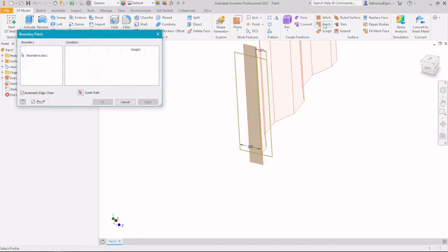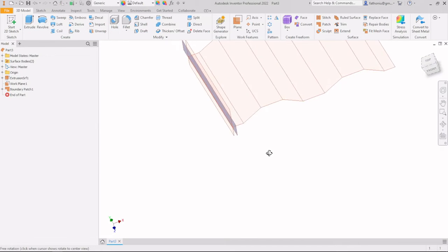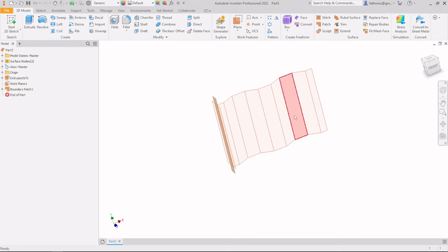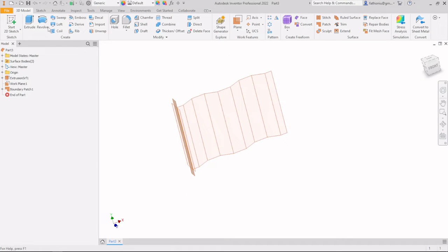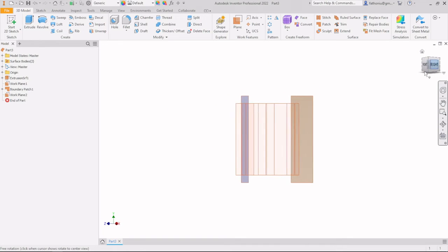To create the surface here, use the patch, select these two patch, click, and okay, then it's converted into what we call a surface. Okay, then same process, we set the plane to this line, and then about the surface 90 degree, yes, there. And after that we go for the surface.